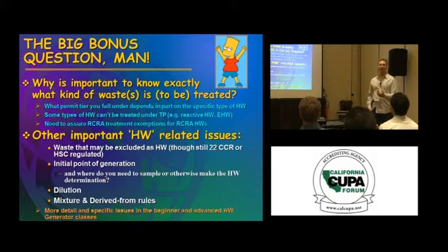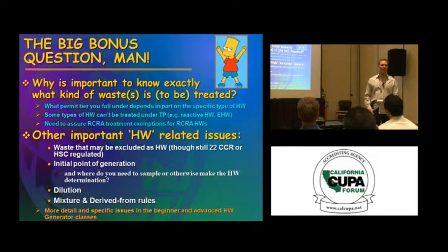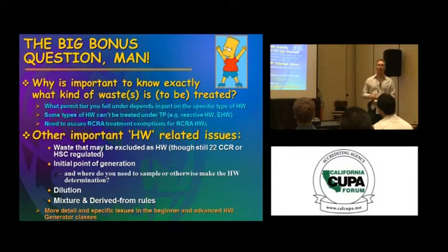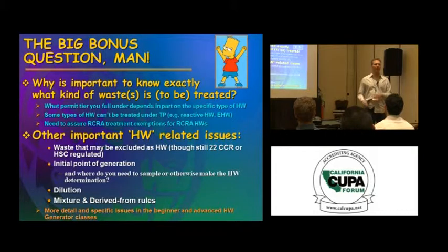So if you're doing sampling, what's the minimum number of samples that you need to take to get a statistically valid result? Three. You can't do fewer than three samples. So if you're an inspector and they're saying, well, I'm not PBR, I'm CA because the concentration of my waste is low, they need to be able to prove that to you. So let me see the lab results.